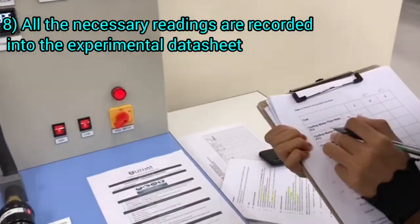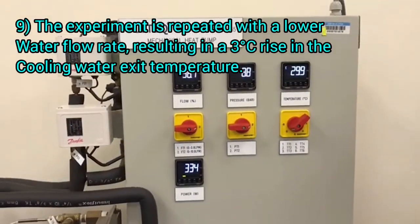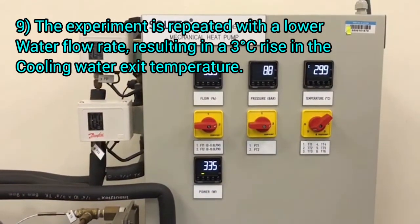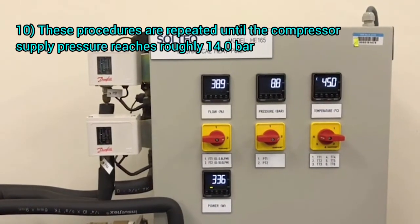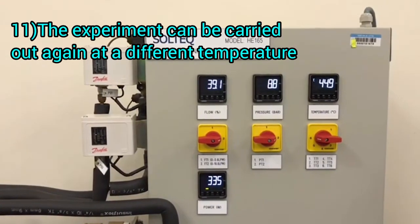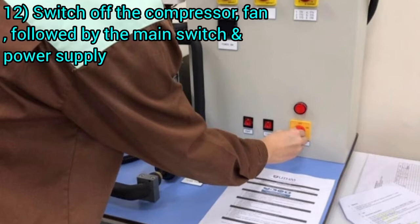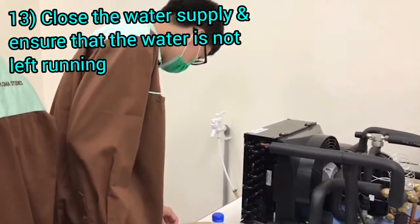Next, all the necessary readings are recorded into the experimental datasheet. The experiment is repeated with a lower water flow rate, resulting in a 3 degrees Celsius rise in the cooling water exit temperature. Next, this procedure is repeated until the compressor supply pressure reaches roughly 40 bar. Next, the experiment can be carried out again at a different temperature. After completing the experiment, switch off the compressor and fan, followed by the main switch and power supply. Then close the water supply and ensure that water is not left running.